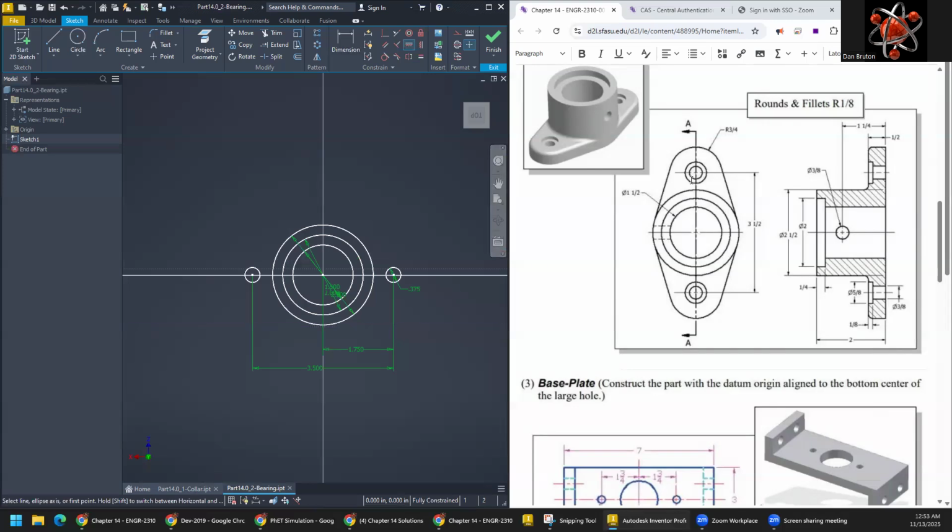Now from those, we have some circles that go out here. We can either make them arcs or we can make them circles that we can just trim. I'm going to start with arcs and just put some out here and out here. Then I can connect this one with somewhere over here, and I like to make it purposefully left wrong. Now that one was horizontal, so that's not a purposeful random line. That's more what I'm talking about there. You want to avoid any kind of constraints going in because you want control over those constraints.